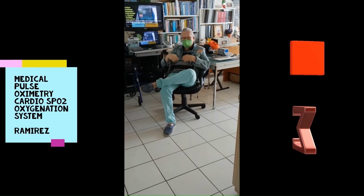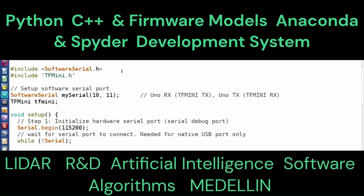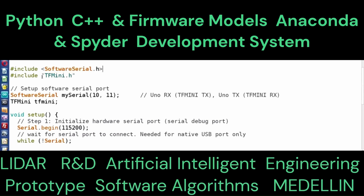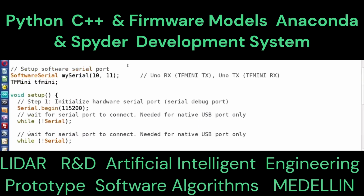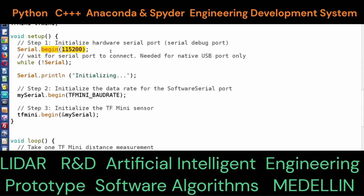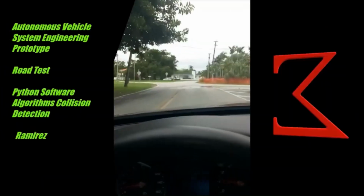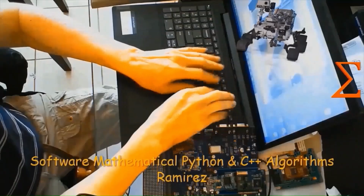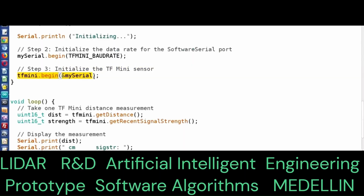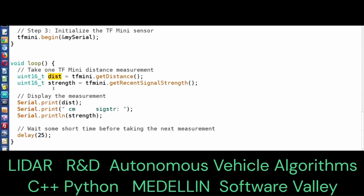As a result, the distance to the detected object can be easily computed because it's represented by half the round-trip time delay, which is formulated as R equals C over 2 times TOF, where R is the distance to the target, C is the speed of light, 300,000 kilometers per second in vacuum, and the time of flight, TOF, is the total time elapsed between the emission and detection events.